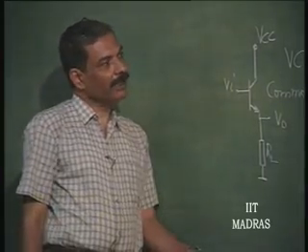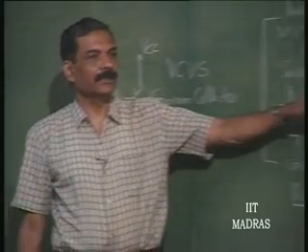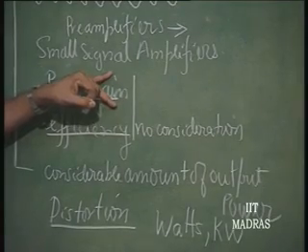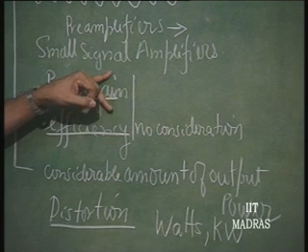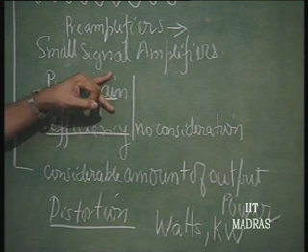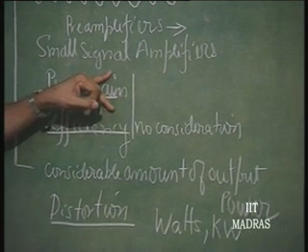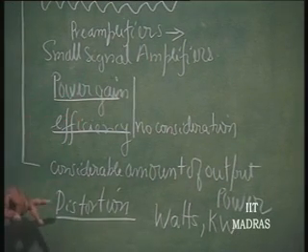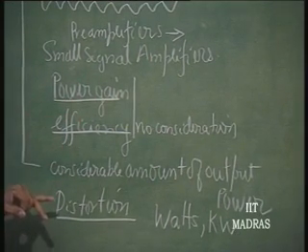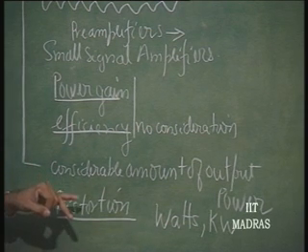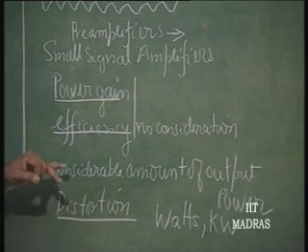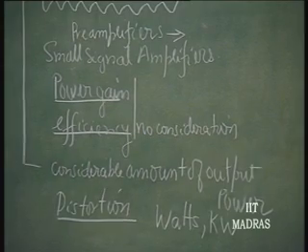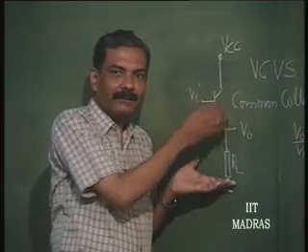We cannot do the analysis of this kind that we have done in the previous stages, replace the thing by a small signal equivalent. It is not, because the signal is varying considerably, and therefore, in power amplifier analysis it is futile to discuss distortion without considering the nonlinear aspects of the device.